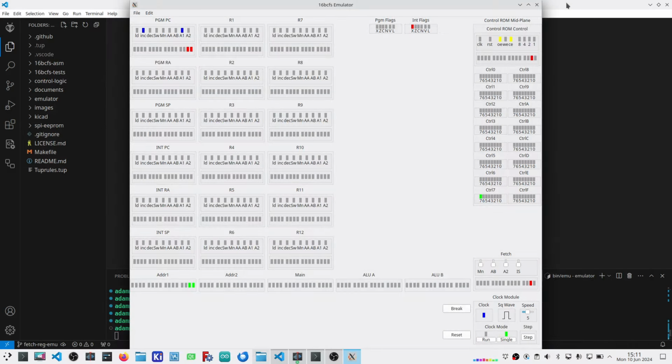And of course, if I run into a problem, I'm going to have to figure out how I can bodge that. That then takes care of all the open issues except for changing the output from the fetch register to be the input into the instruction register, which hasn't been created yet. But I'm going to create a purpose-built bus just for that particular case and then get that wired up. Once I do that, all of this up here in the corner is no longer going to be operational. It's only ever going to show the no-op instruction. Let me get that done.